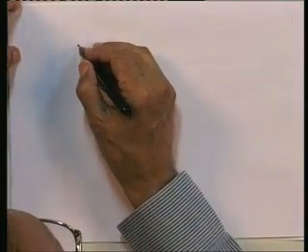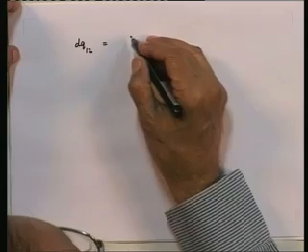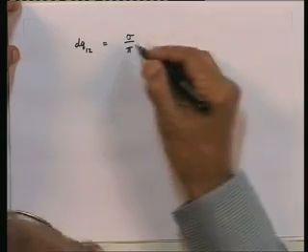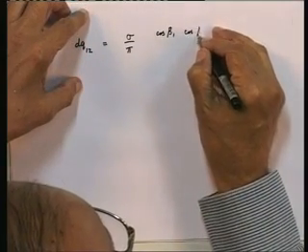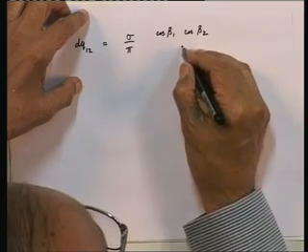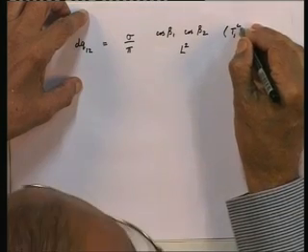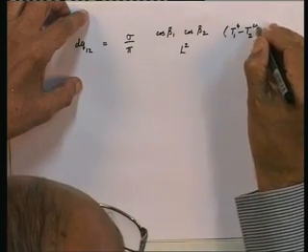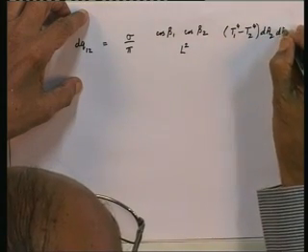The expression which we had derived last time for heat exchange between two differential areas dA1 and dA2 was dQ1 to 2 is equal to sigma by pi cosine beta 1 cosine beta 2 divided by L squared, multiplied by T1 to the power of 4 minus T2 to the power of 4, dA2 dA1.